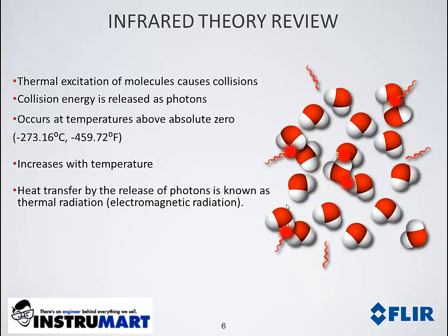And as these molecules move around, they collide with each other, creating a release of energy in the form of photons. As the temperature of our medium increases, so do the molecular collisions. Thus, an increase in temperature produces an increase in collisions, resulting in an increase in the release of photons. This form of heat transfer caused by the release of photons is known as thermal radiation or infrared radiation. Now, this thermal or infrared radiation is what is sensed or seen by an infrared camera.